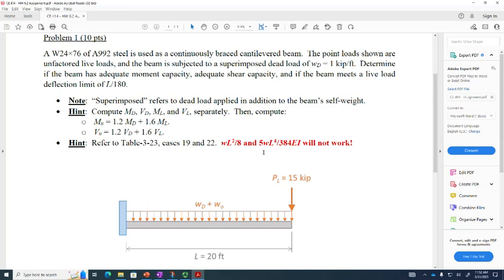Yes. There is a difference between whether or not the beam is going to actually fail and collapse and kill people versus if it's literally deflecting too much. As an example, L over 360 deflection limits came from plastered roofs, because if you exceed L over 360, you start cracking the plaster. Cracking the plaster does not mean the beam is going to fall down and kill people, but you don't want to crack the plaster. So I'm saying, quote unquote, we needed to upsize this beam to make sure we didn't crack the plaster. That's what I'm saying.